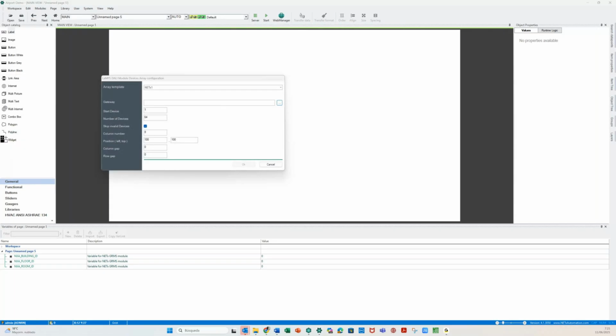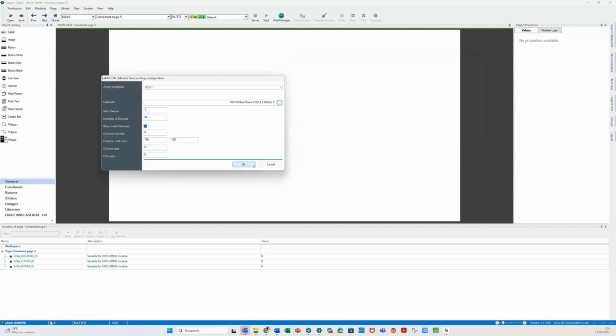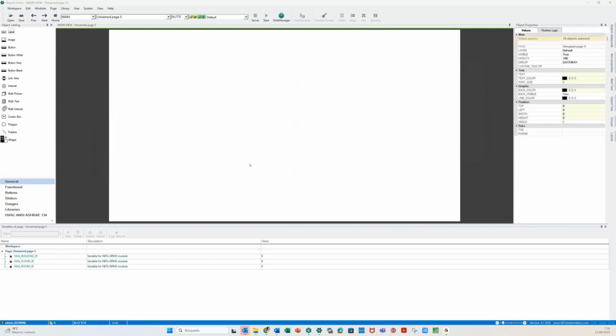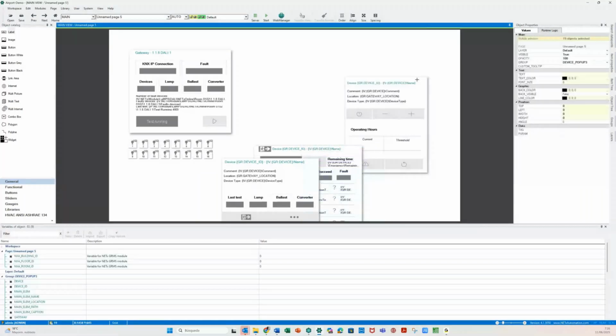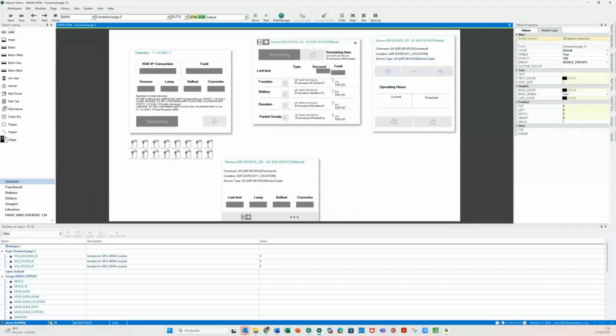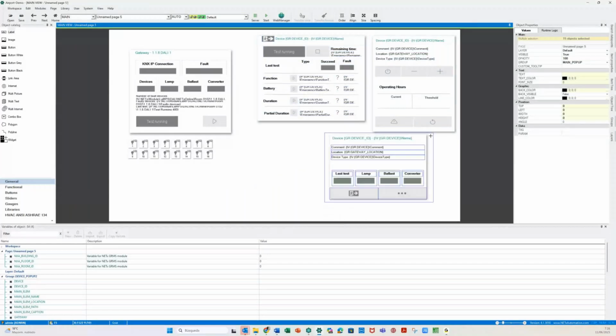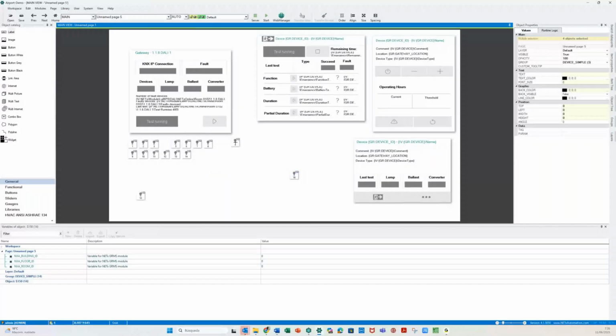Okay, now it's here. Select the gateway, for example, this one, or maybe this, that has more devices. And then you have here your whatever number of devices, 1 to 16, and then you have these possible options to see if you select your lamps, whatever. If it's an emergency or normal, it's a pop-up window, so you can distribute your lamps in the layout of your background, whatever.